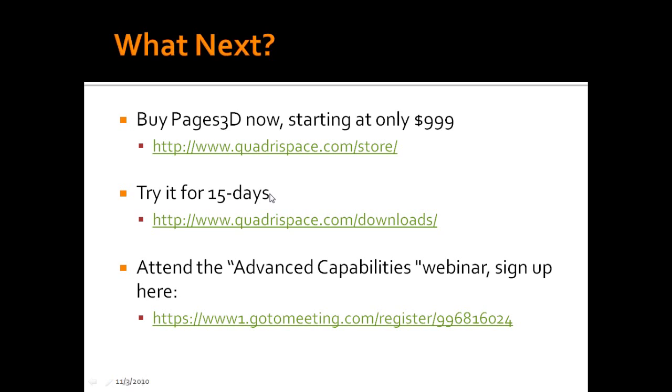Let's see. Any way to create notes with leaders? I want to point to a specific component and provide some information about them. Certainly. The way we did callouts and ballooning, it's a very similar process to create notes. The notes can be text that you would type in yourself, or the text could be based on metadata that you might import from either a PDM or a CAD system. Sorry, I'm running out of non-scratchy voice here. Yeah, you can drag off notes as much as you want.